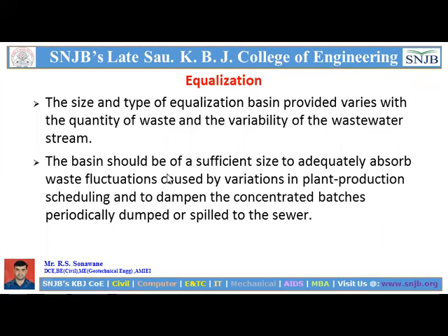The size and type of equalization basin provided varies with the quantity of wastewater and variability of the wastewater stream. Just as I told you, equalization is to retain the waste in the basin of a particular unit, so there are two systems, inline and offline.